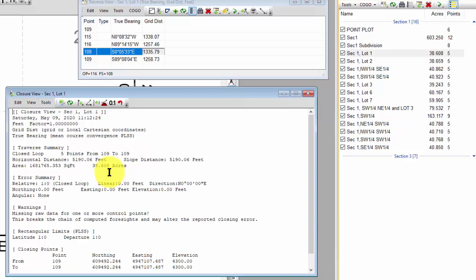So they said, oh, we can do a compass rule adjustment and that'll get us close. The problem is that's all it did. It really only just got us close, and it was kind of a farcical way of coming up with what the area should have been. And I wanted to show you this because now I'm looking at grid distance, okay, and I've got this area that's wrong. I could do a ground distance based on planar computations, and I still wouldn't get the exact right area because I'm not accounting for the convergence properly of the east and west side of that part, okay,